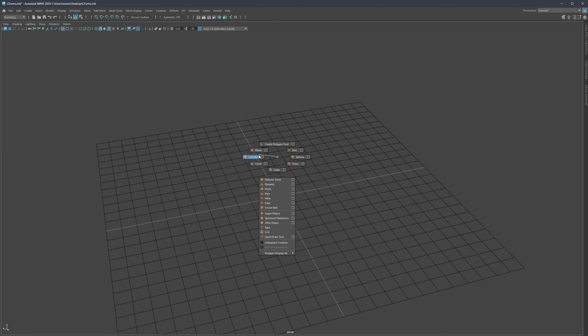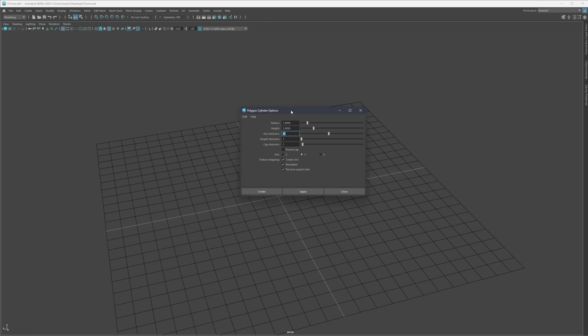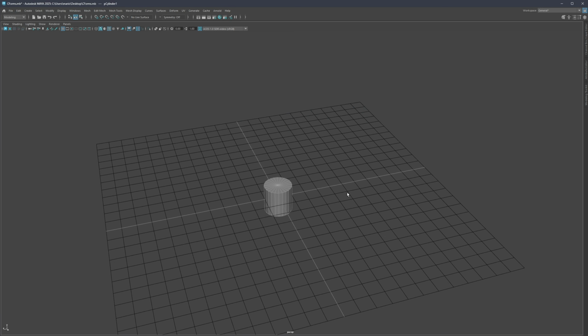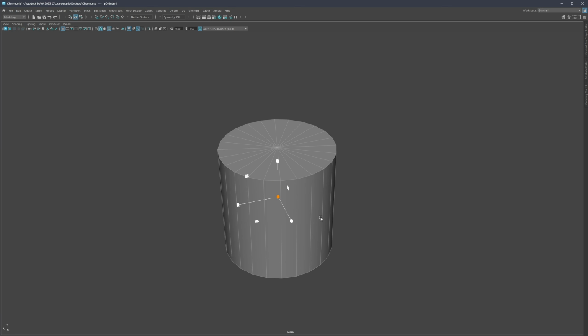So I'm going to start with the cylinder, 24 sides. Usually with cylinders, this is also good practice that I recommend, when you're practicing cylinders, try with 20, 24, 28, and 32 sides. So this is going to be the golden middle. And then from those, you're going to either subdivide further if necessary, or just leave them as they are. So usually I start with 24. This is the golden middle that I usually go with.